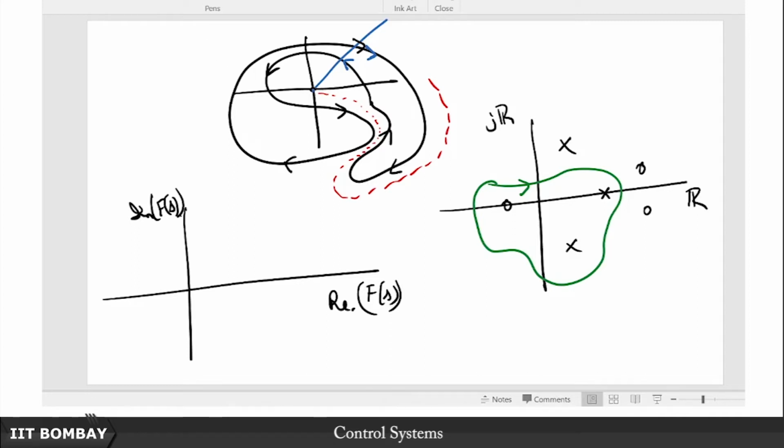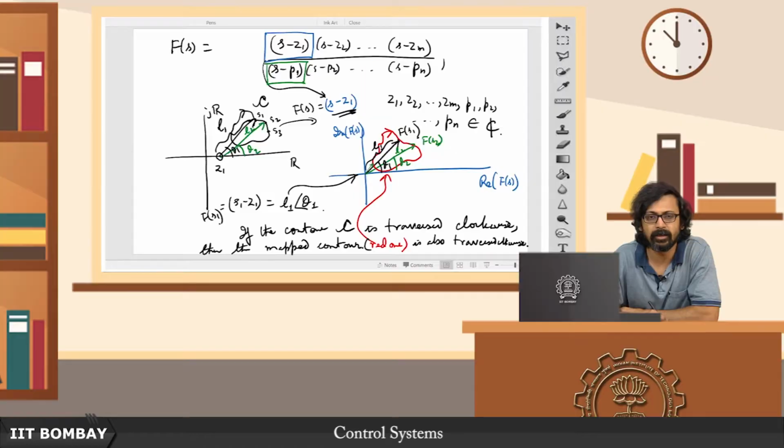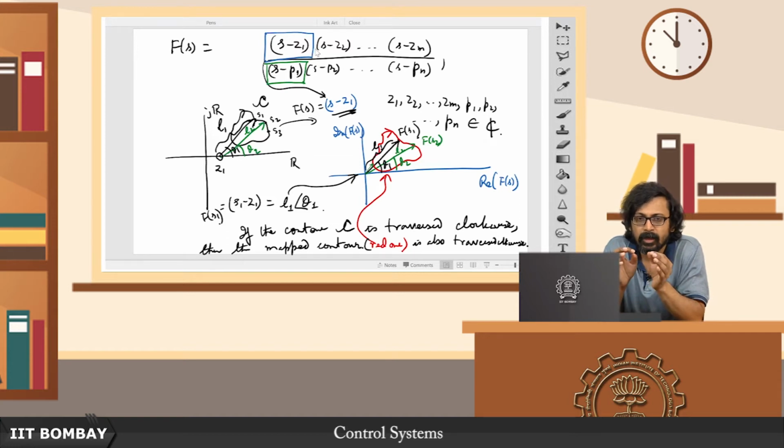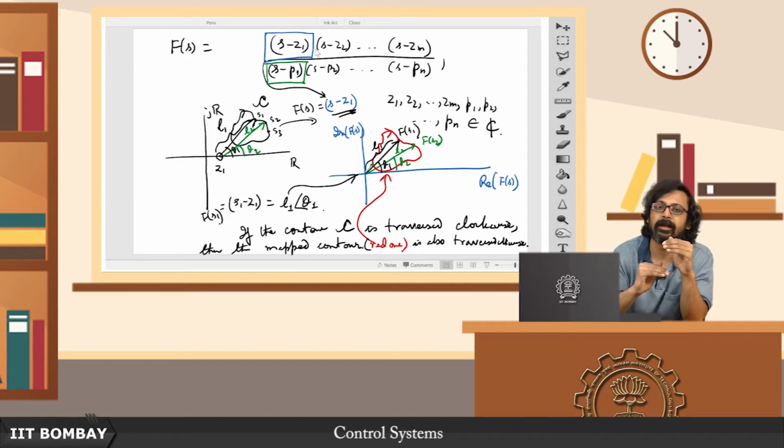Cast your attention back to a typical transfer function that we considered, such as this. The important thing to remember here is that the net argument or the angle of this function Fs is the sum total of the contribution of those individual blocks, right. Everything in the numerator, those 0 blocks, they get added, and everything in the denominator, the pole blocks, they get subtracted from there.